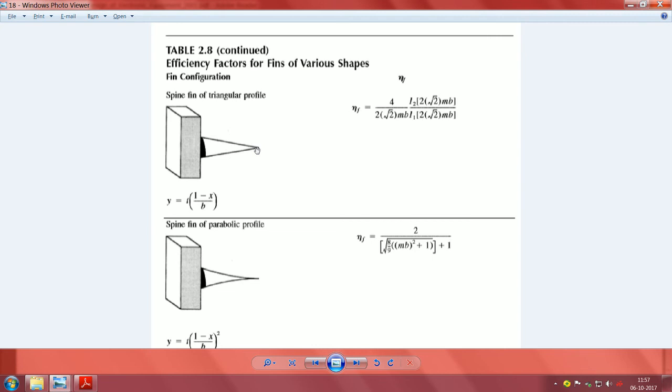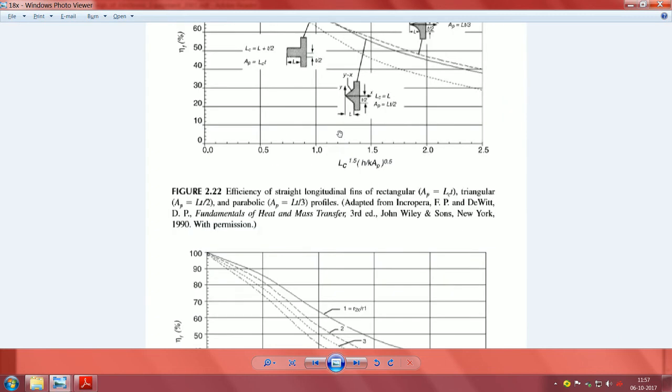So, go and check out a fan with a Pentium cooler, and in case you do not have such a device and you want natural cooling, probably you can have a heat sink which is extruded with tapered fins. At least in one of the directions you can have a tapered fin rather than a spine fin, and in the other direction you make spaces, and sometimes it is done at an angle. We still have the advantage of having a lot of these things.